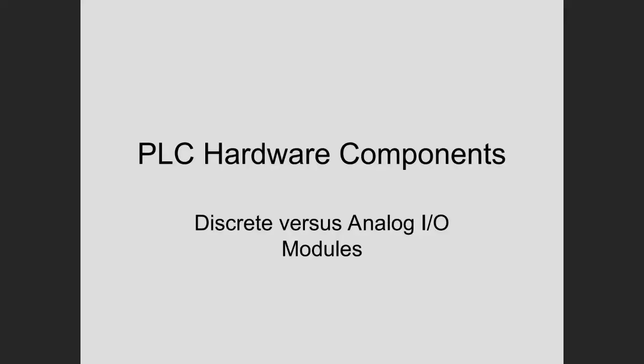Okay, so now remember what we're doing. We kind of gave you an overview. I showed you a picture of a PLC because I'm not in front of you. I couldn't bring the actual PLC in to point to it, so I showed you a picture. We identified some major parts of the PLC: the input modules, output modules, call it the I/O section. There was a CPU as an important section. Power supply is an important section. There's a communication module. There were different parts that we pointed out on that modular PLC that I showed you.